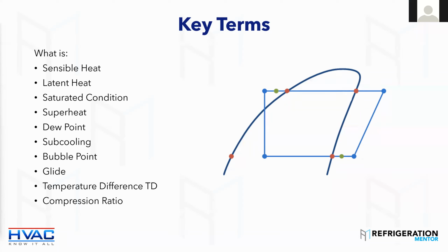Absolute discharge pressure divided by your absolute suction pressure. 100%. And that's so important to know, because one thing that I didn't really understand and take into consideration when I was troubleshooting systems in the field for many, many years is compression ratio. And when I worked for a compressor manufacturer for many years, that's where it really hit me and I realized that compression ratio is so important.